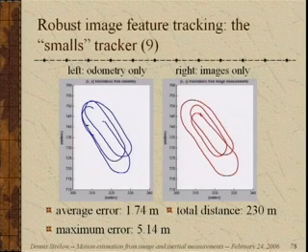So the idea of SMALS was that we're going to use its output as the input to our 6-DoF motion estimation. And these are the results of that motion estimation shown from above. The graph on the left is the ground truth odometry from Hyperion. One reason we're doing 6-DoF motion estimation is that odometry does drift over time. But over the scale of this example, and given Hyperion's magically good odometry, we found that the estimate on the left is almost exactly the correct motion. The estimate on the right is what we get by feeding the SMALS output into a Kalman filter. It doesn't have any gross local errors, but it does drift over time, and I'll come back to that.